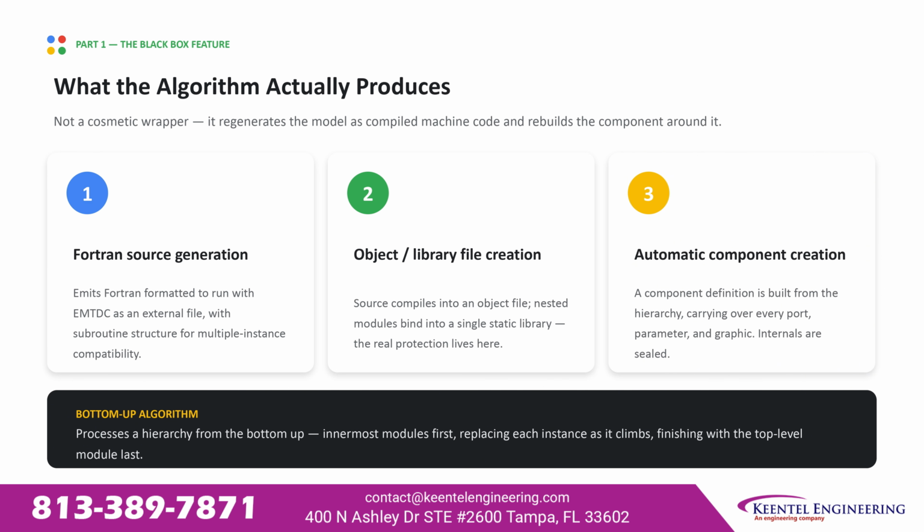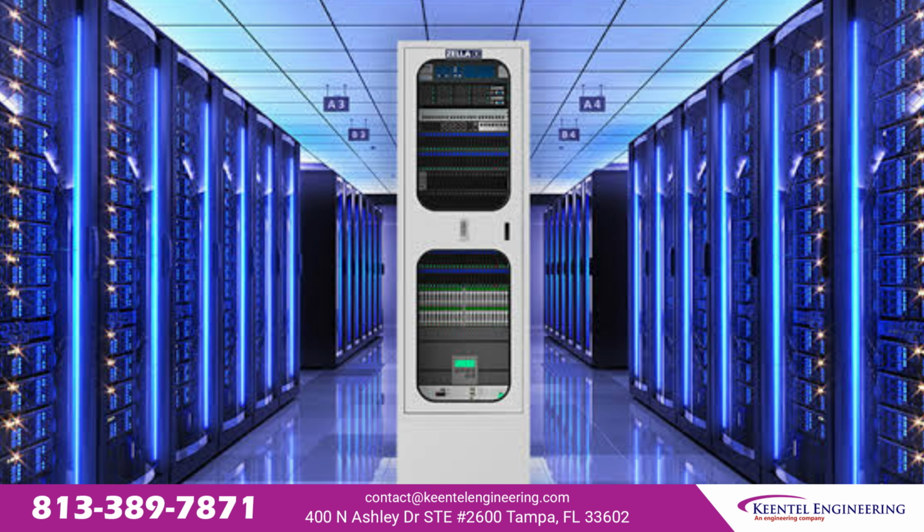Third, automatic component creation. A new component definition is built from the original hierarchy, carrying over every port, parameter, and graphic. The internals are sealed. The algorithm processes the hierarchy from the bottom up, innermost modules first, finishing with the top-level module last. A deeply nested control structure is fully absorbed into the compiled output with no intermediate layer left accessible.